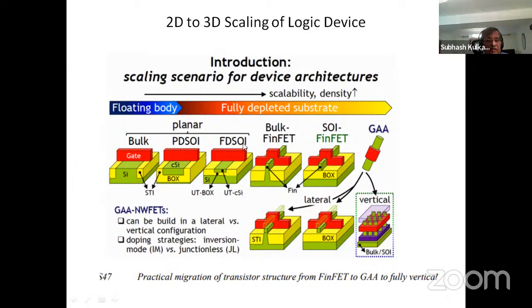SOI is silicon on insulator. So you have this silicon and there is an oxide on the top, and then you have this silicon layer on the top of it. And this is how the material starts. And this isolates the substrate, and you have better performance of the device, especially in the RF applications, where you need really noise-free